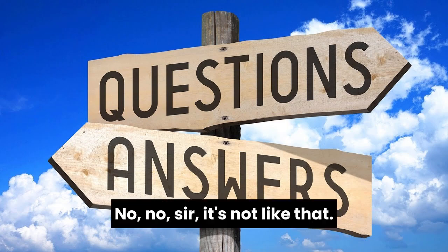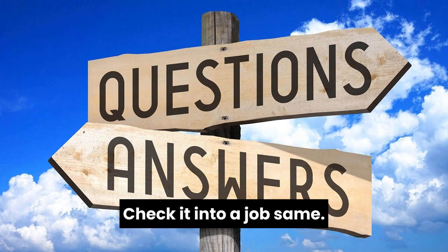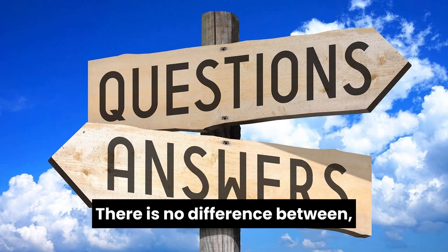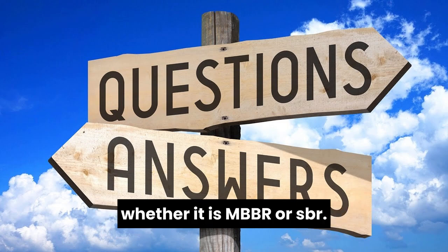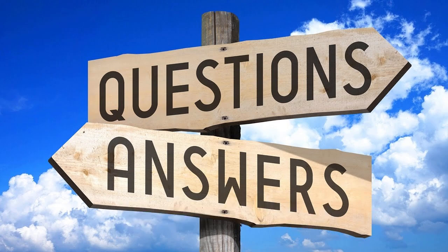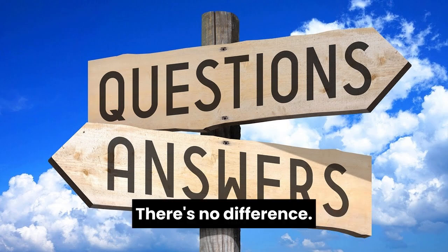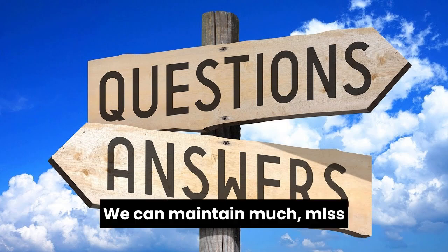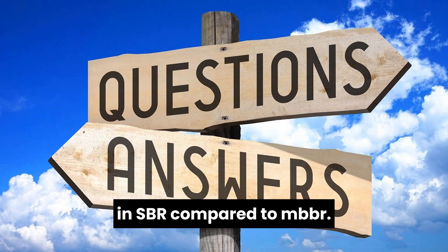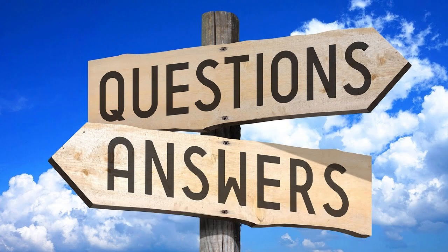No, sir. It's not like that. You have to take a sample and settle it, check it in a jar, same as with MLSS in MBBR. There is no difference between checking MLSS whether it is MBBR or SBR. Conceptually, it is the same. Sir, we can maintain much more MLSS in SBR compared to MBBR.